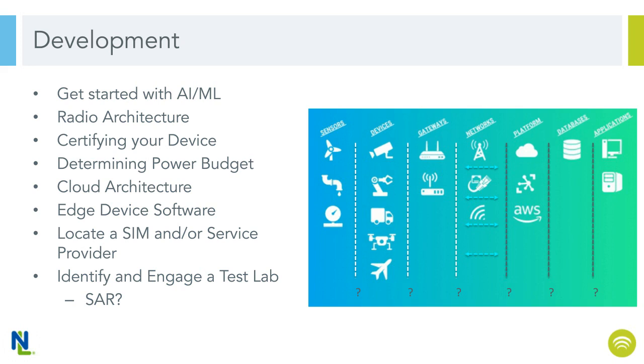Most cases, we're talking about little sensor nodes that are sitting out there on the internet in some way with a cellular connection or a short-range radio connection into a gateway of some sort. And you want that device to be able to continue to work on a battery for 10 years, 15 years, whatever the case may be. So managing the power and knowing what your budget is for power is critically important. So if you know that ahead of time, all of the decisions you're making when it comes to picking components and picking radio standards and determining how often your device will wake up and what parts of it will wake up, are all pretty critical to making sure that you've got a device that will fit within the power budget that your device needs to have.